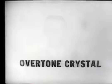Earlier in the lesson, we discussed the various crystal cuts and how each was different from the other. However, they do have one thing in common. That is, they can be made to oscillate at frequencies other than that frequency for which they were cut. Now, when a crystal is used in a circuit in this manner, it's referred to as an overtone crystal. An overtone crystal.